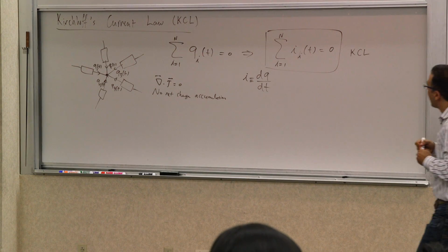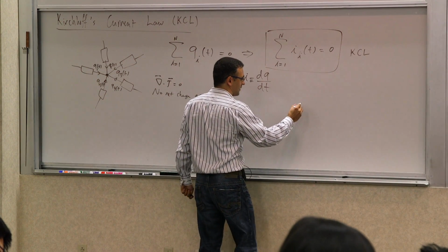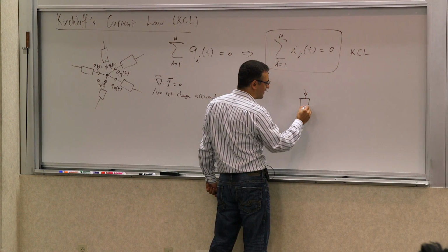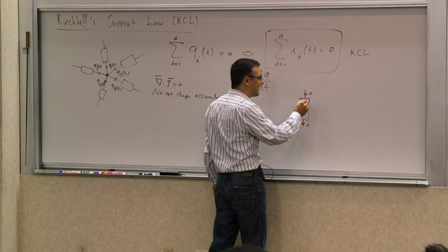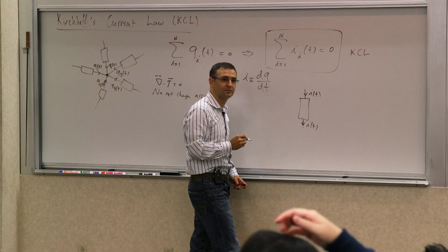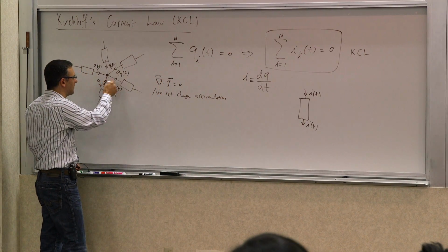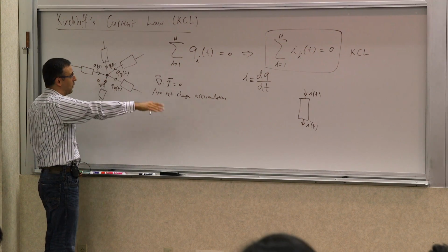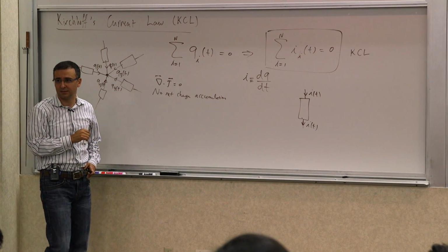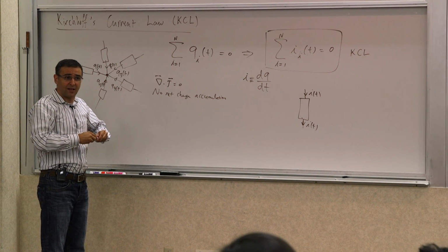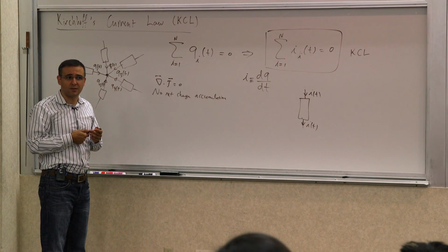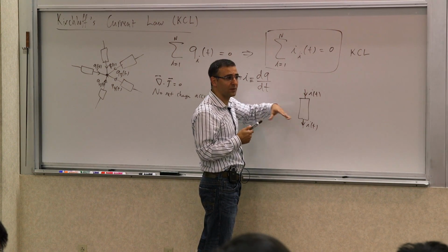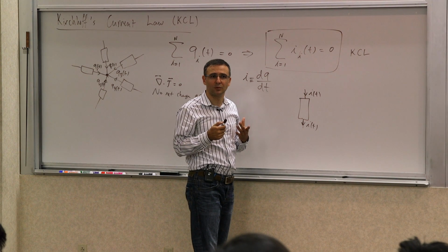Also keep in mind that when you have an element, within the circuit domain, this current and that current are instantaneously the same. So because of that, the current that comes out of this side is the same current that has gone through this side. And that's important when you look at the overall accounting of all the currents everywhere, at every point. Now, that's not necessarily true. I gave you an example last time of where this is not true when you don't have the circuit assumption. What was the example? Does anyone remember?